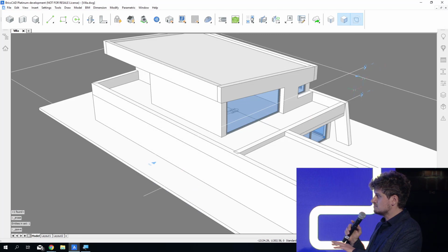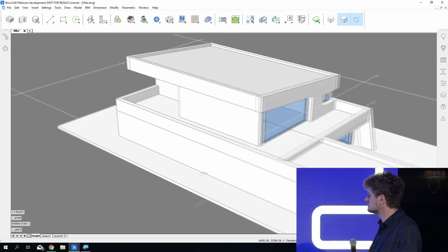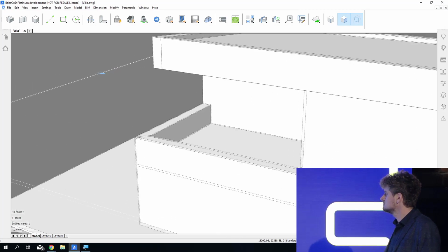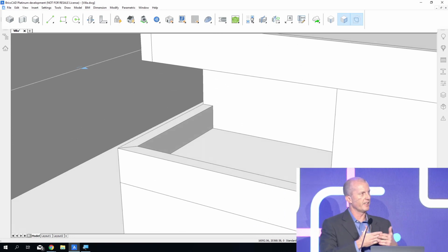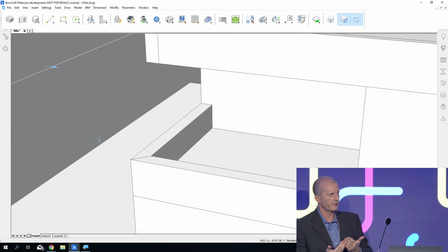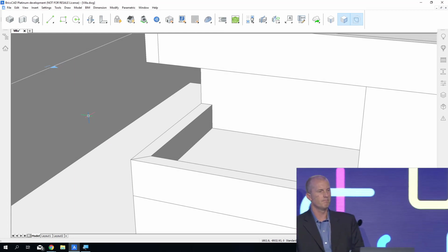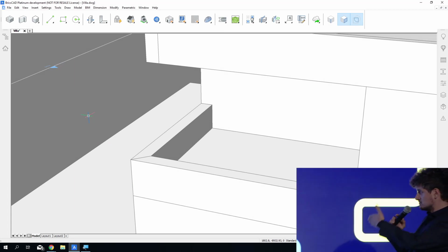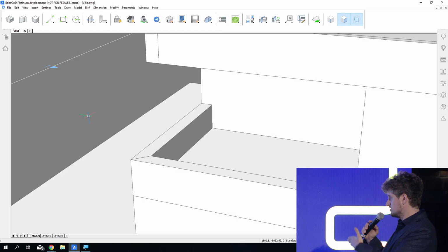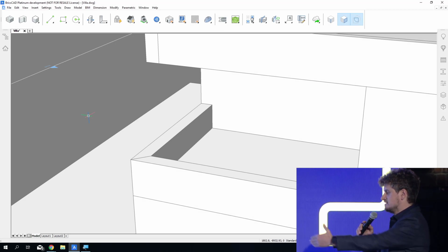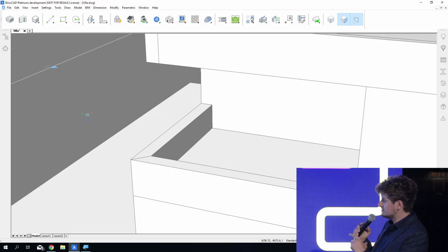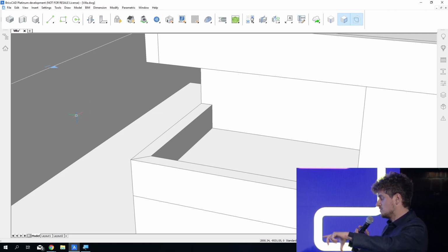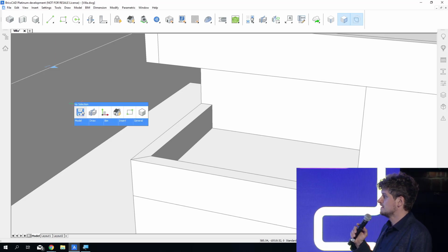And check, just to clarify, so Jacob was showing that insulation block that's continuous, so the model is changing all across the length of that, not just at where the section is cut, is that correct? Yes, indeed. This detail was found on a section between the walls and the slabs. Therefore, it knows that it can be elongated along the length of that wall. So therefore, it can adjust its length everywhere in the model to all the lengths of the wall.